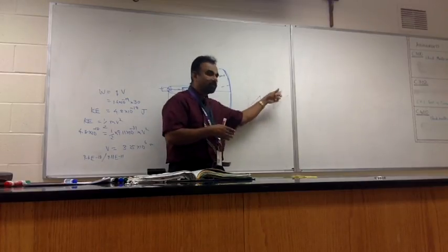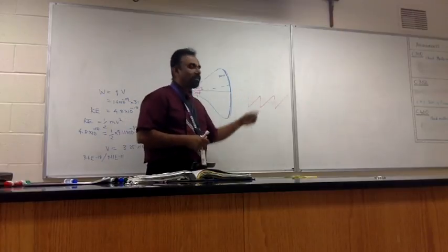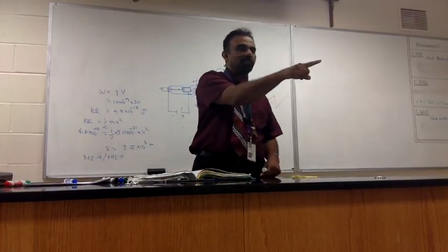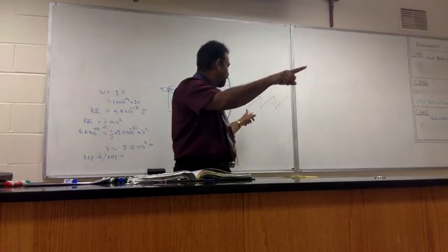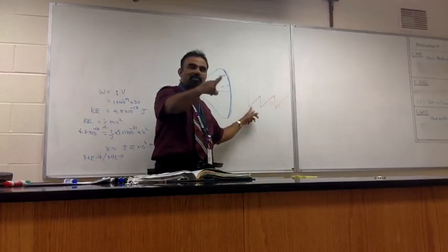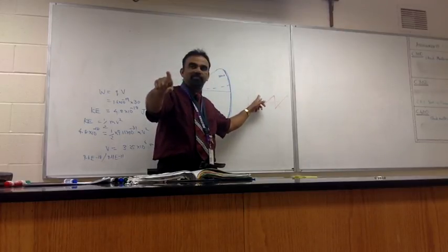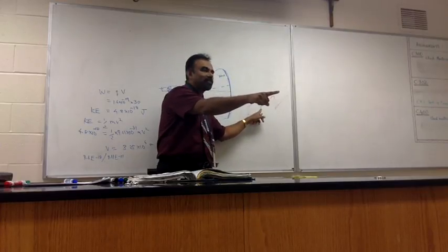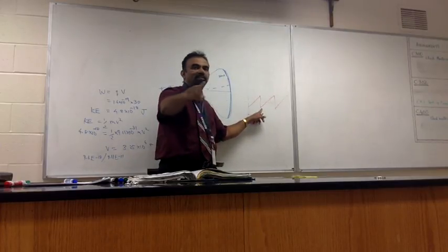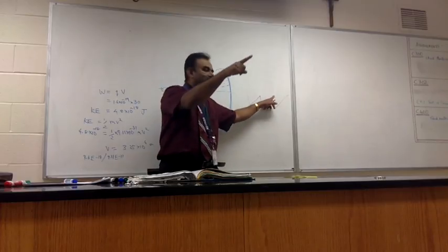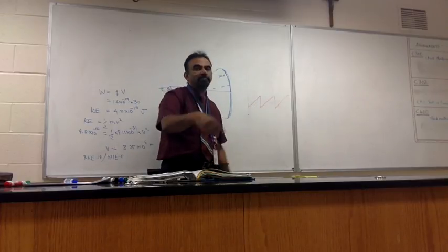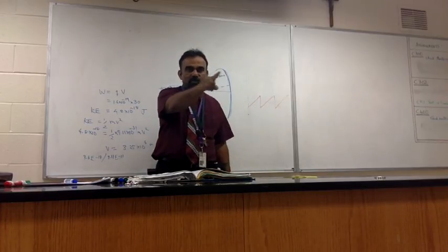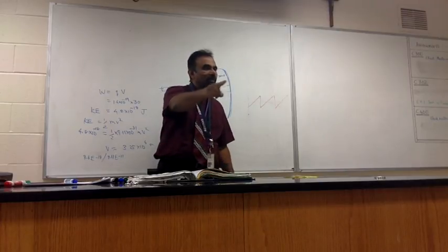So when we give this signal, what will happen is the spot from the left hand side will scan on the screen to the right hand side, and then all of a sudden go back to the left hand side. See? And then again scan till here, and again all of a sudden go. So you'll see the spot going to this side, quickly coming back again and going, scanning again, scan again, scan again.